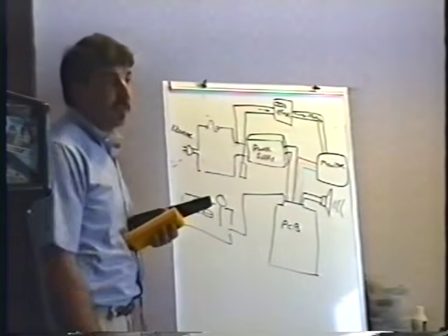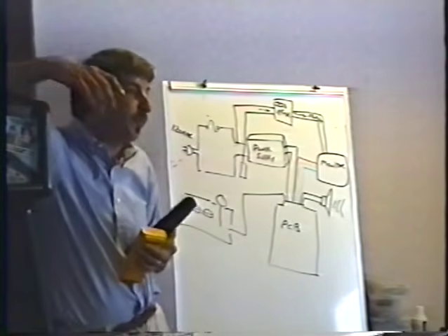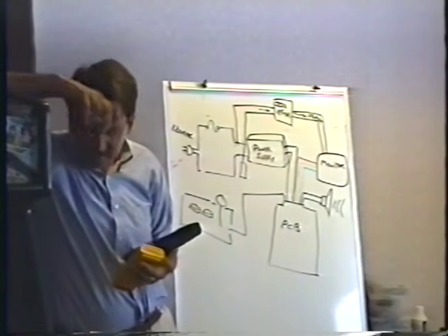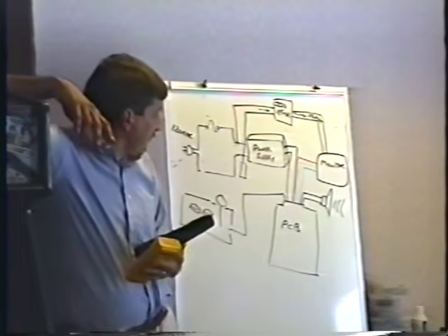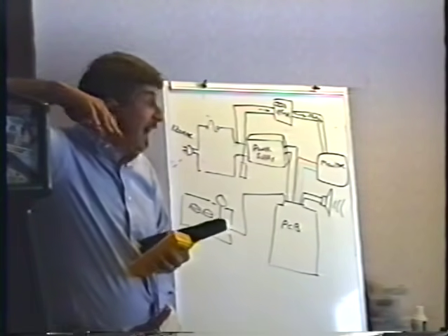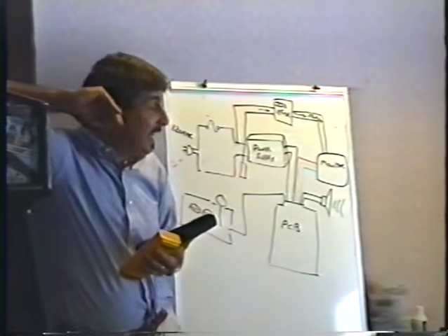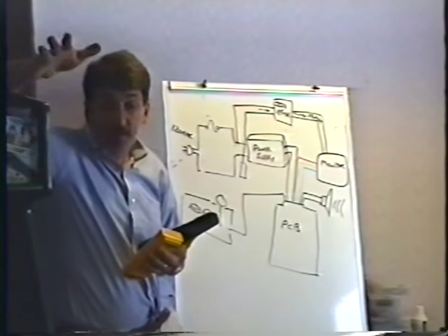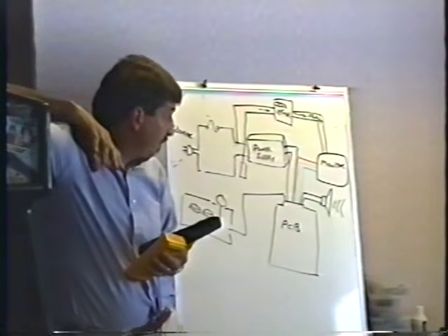So by coining up, I know it seems so simple. You coin up the game, you press the start button. You'd be amazed how many people don't think to do that. I mean, it's such a simple thing. So if you get no game sounds at all, you probably have a power supply failure. If you get all the game sounds but no picture, it's probably a monitor failure.